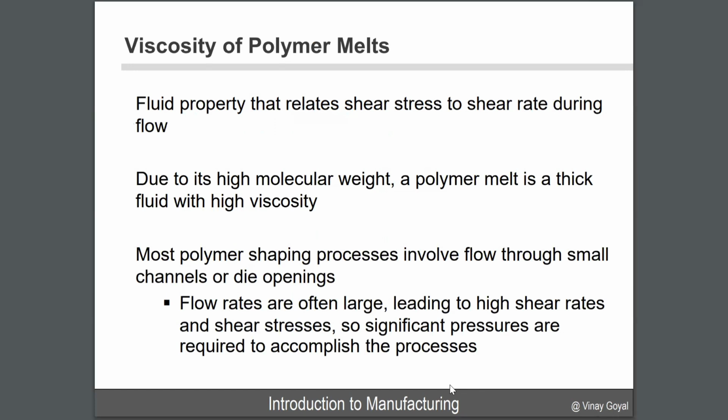So think about a very rubbery substance that when you increase the amount of heat, the polymer material behaves a lot softer. So it's going to be a lot easier to shear the material because it's softer. And that's related to the shear rate, which is also related to flow. So a polymer at high temperatures will be a lot easier to deform, especially under shear deformation.